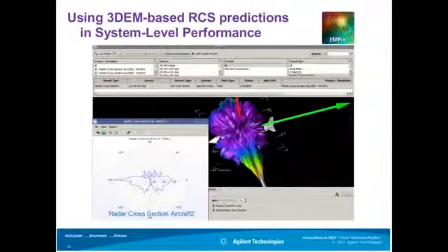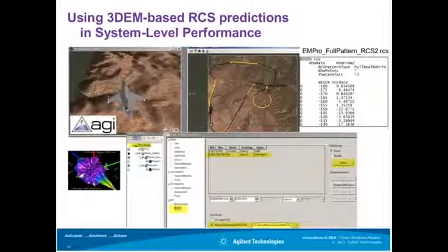Okay, another interesting technique here is that we used our EM Pro package and generated a 3D radar cross-section of an aircraft. And then I introduced that 3D radar cross-section data into STK and integrated it in at each of the phi and theta values.